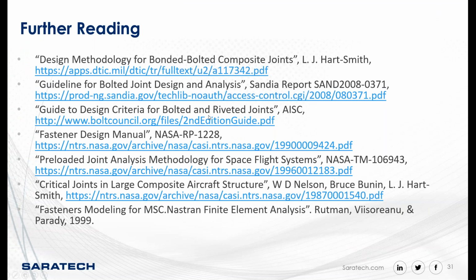And the next question is, is there an advantage or disadvantage to using beam elements instead of bar elements for the fastener between the RBEs? Good question. Bars versus beams. I tend to go to a beam element in general. Why? Because the beam element has more options. Even if I'm not using those options, things like tapering and so forth, I still have the ability to just modify the property if I want to turn any of those options on. And then, if I do a nonlinear analysis, bars are not a nonlinear element, whereas a beam is a nonlinear element.